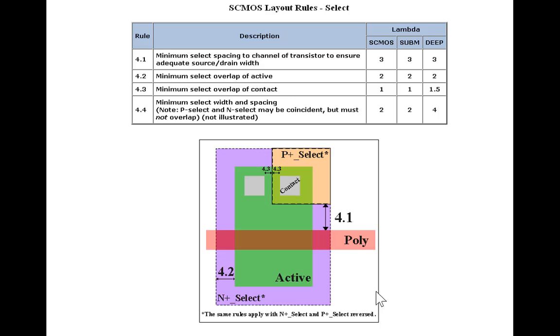Now Cadence 6, when you use the Virtuoso, when you go into Virtuoso, on the left side you have all the different drawing layers there. When you select one, when you click on one, then you are going to draw that one. When you click that one, all the related design rules are activated. Okay, so now when you use your mouse to draw, for example, if you draw N well that's too small, then it will immediately tell you it's too small.